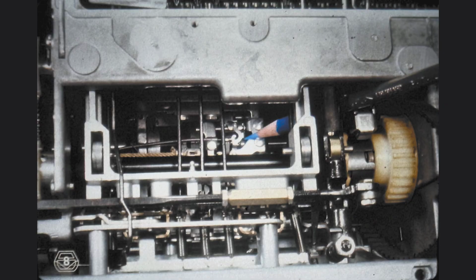If you move the carrier of your typewriter over the cycle shaft cavity, you can see the bottom of the carrier and then locate the indicated roller on the print cam follower. Be sure to notice that this small roller can move sideways on the shaft of the print cam follower. This feature enables the one cam follower to operate off either one of the lobes of the print cam.